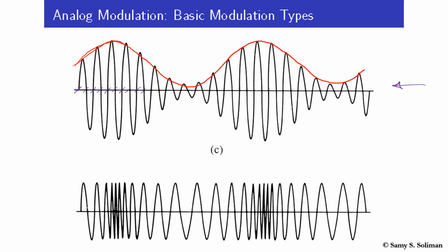In the second example, while the envelope is almost constant, the frequency is varying, as you can see here from the zero crossings. In this part of the signal, the time between different zero crossings becomes less, which means the frequency is higher. Of course, you recall that frequency is inversely proportional to the period, and back here you get an increasing period, which means a decreasing frequency.